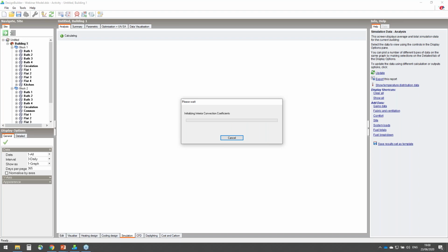So I did not ask for more detailed outputs such as detailed internal gains, surface level outputs, comfort, environmental results, etc. and at high granularity for daily, hourly or sub-hourly time steps. I would have done that if I was analyzing the building performance in more detail. Also, it is a good practice to do a proper QA check of your models before you embark on final runs. This can be done by simulating short time periods at high time frequency, like hourly or sub-hourly level, and ensure that the systems and operations are running as they should. This type of sanity checking, and basically QA checking, is essential when doing proper modeling.